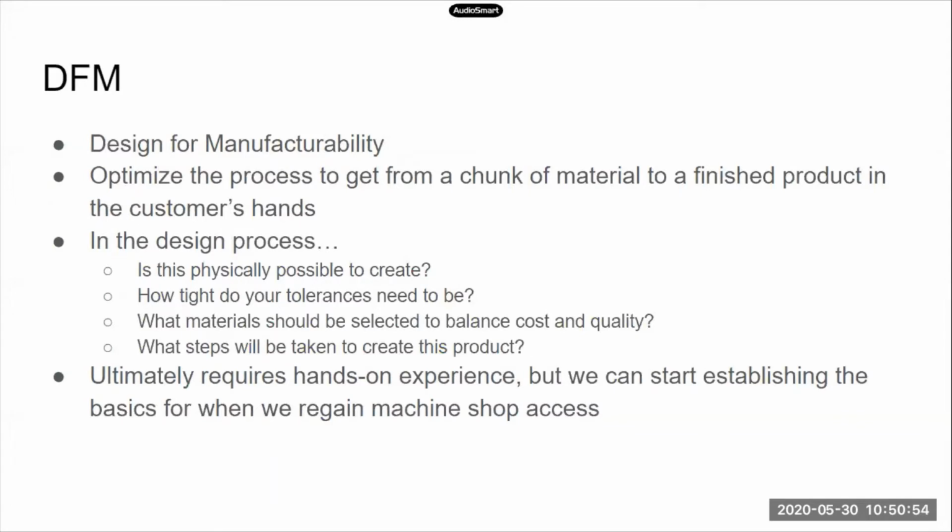And then some other considerations would be how tight your tolerances need to be. A lot of times people may not actually need a super high tolerance, but they'll just throw on a tolerance that's standard to what they're seeing a lot of other times. And if your tolerance doesn't need to be that high, the higher the tolerance, the more cost. So as I said, your main goal in manufacturing is lowering the cost once you've overcome, obviously, the basic criteria of actually being able to create this.